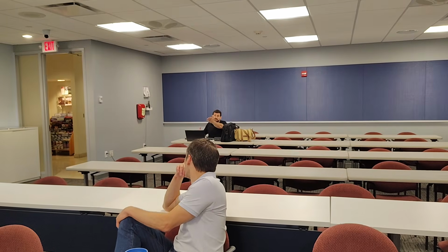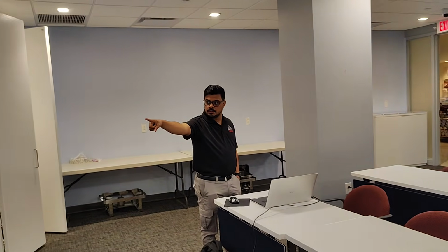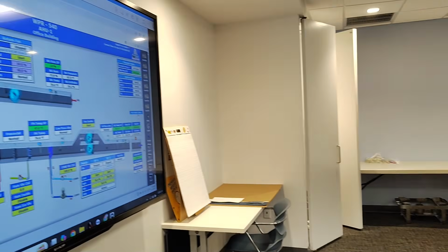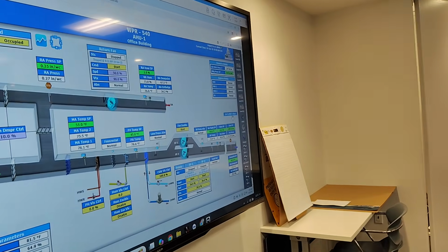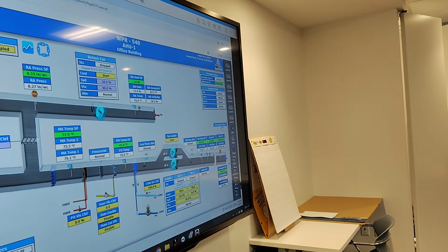All you're doing is looking at it through your new integrated BMS. But that's it. It's just looking at it. We've integrated this BMS with existing controls containing existing problems, like a supply fan that doesn't report status when we know it's on. Because the start set point is at 2 inches of water column, it should at least be at 90%. And where are we at right now? 36%.